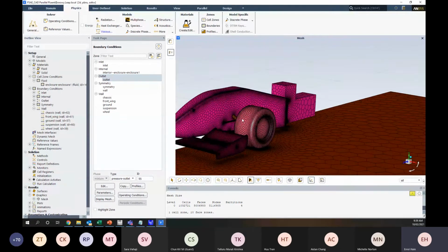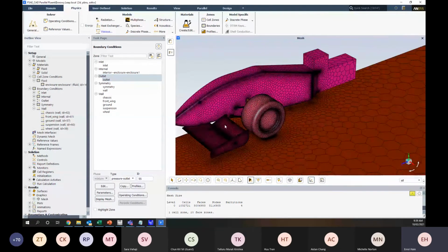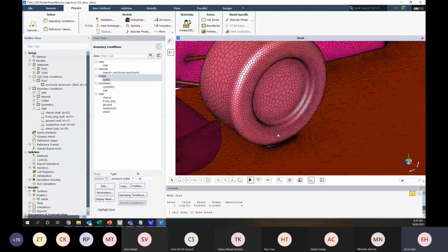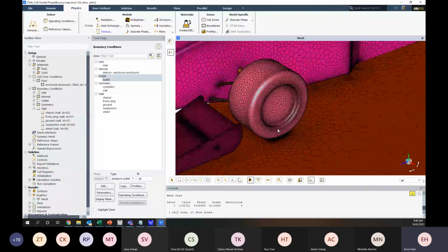You can basically change the shape of the wheel. So if you work from, say, some images that you have of your vehicle going around a track, what the average shape of that wheel is, especially where it bulges out down the bottom, you can build that into the CAD, but we generally won't have a model that's changing as the solution goes. That's a very complex model that requires things like fluid structure interactions. But it's a really good question.